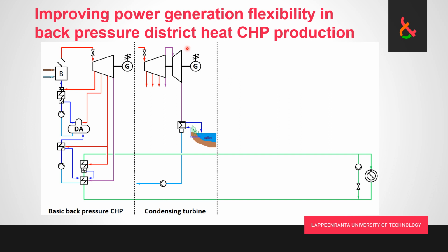Why we need to always run some steam through it is because there is going to be friction at the shaft, and we have to put some flow through it to pick up the heat that is being generated so that we don't overheat the turbine. But we can run only very little steam with low price, and then when we have high electricity price, we run as much as the plant can produce and as much as the turbine can take.